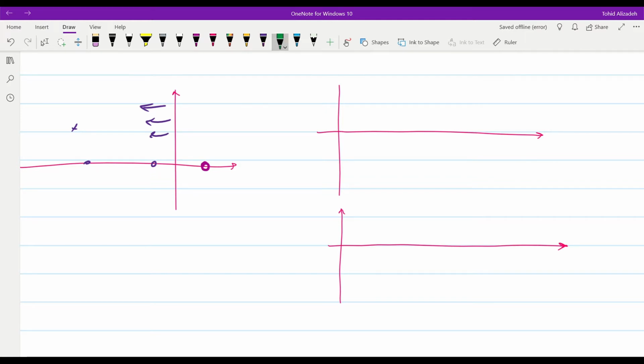So let's say here we have Z1 and we have the second zero, both of them at the same frequency, one on the right side and one on the left side. Here we have, let's say, 1 and -1. In terms of the amplitude, for both of them we will have the same amplitude graph, with 20 decibel per decade in terms of the slope of that part of the Bode plot.